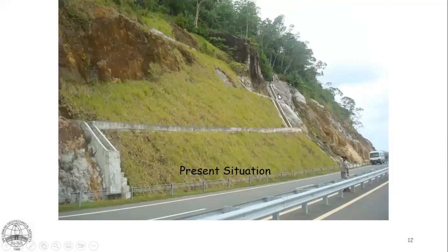Now, the same section, after implementing all proposed drainage measures, you can see these cascade drains bring the water down, and then water comes along this berm drain and gets out to the road drains here. So we have to have cascade drains at appropriate intervals, having assessed the quantity of flow. Right?